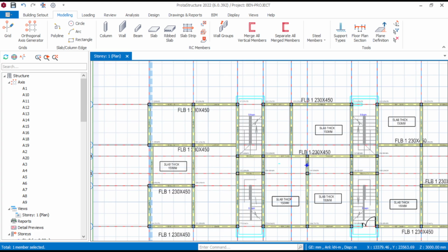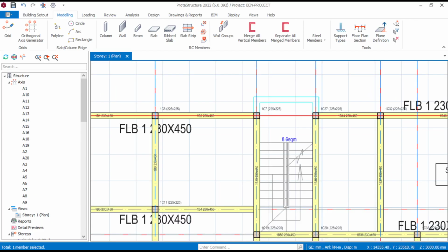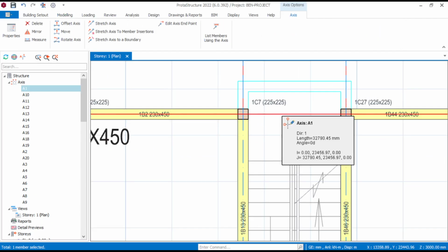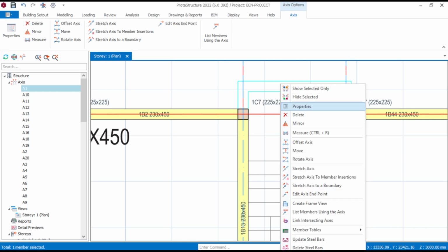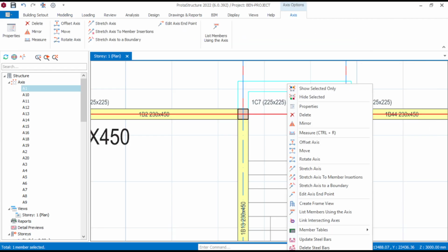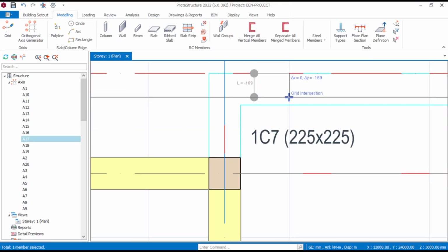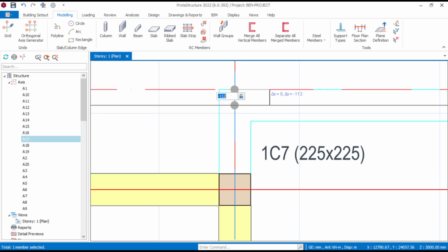Now let's come to this place. Now remember I told you in part 1 that these beams here are actually going to be transfer beams. What I mean by transfer beam is that we'll have columns that would actually be starting from that beam. Those columns are floating columns. They won't get down to the foundation. So let's get the center line, shift F2, minus 112.5.